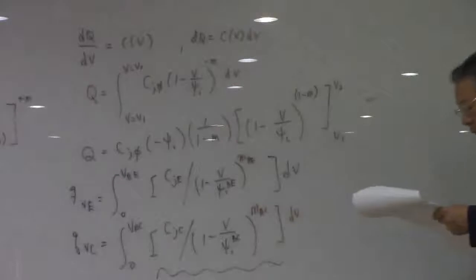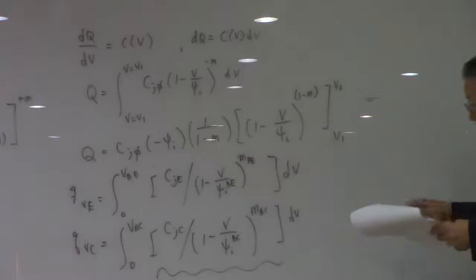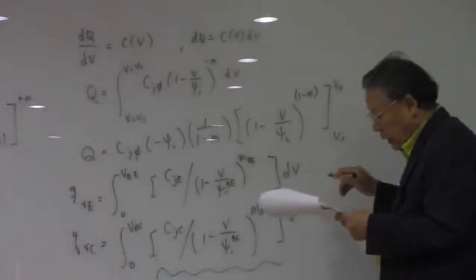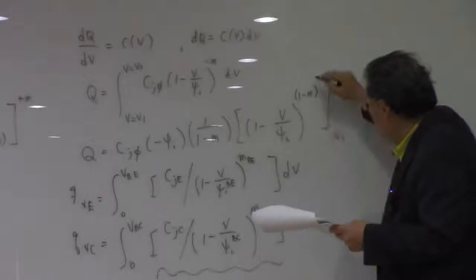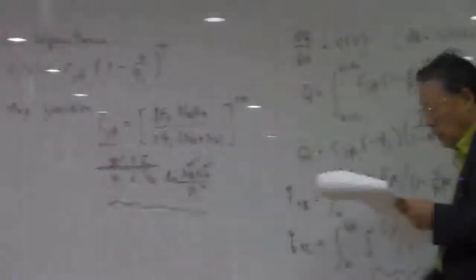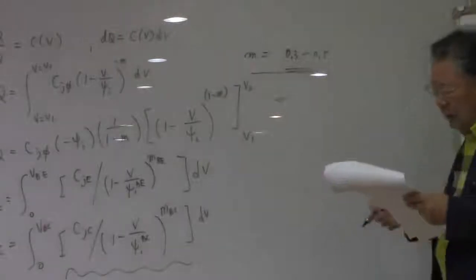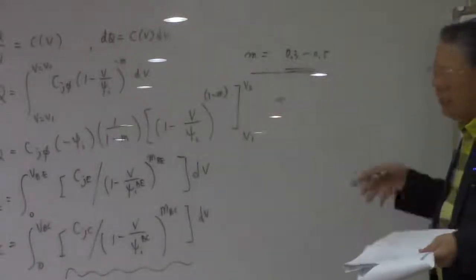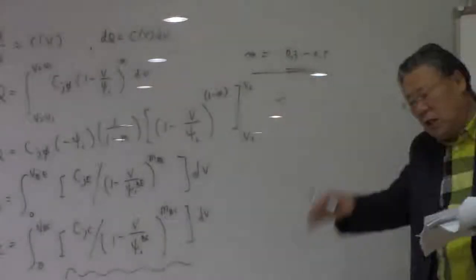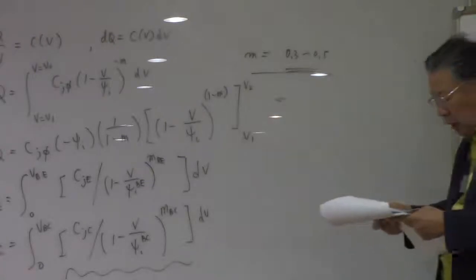The junction capacitance is going to change with the applied voltages. M is about 0.5 in step junctions, but usually it has to be determined empirically, between 0.3 and 0.5, depending on the device, because you cannot exactly control the slope of the dopant concentration in the junctions in the real process.